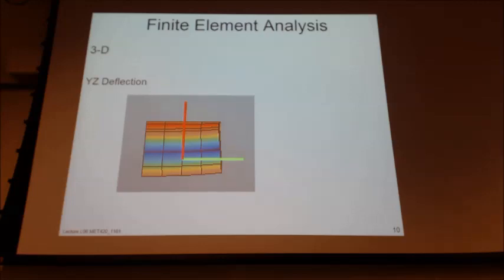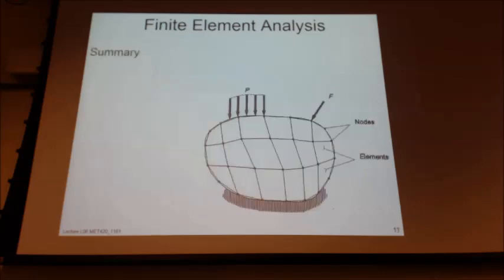And we remember from that graph that I showed last week or so, until you get out to about a 10-to-1 aspect ratio, shear plays a role in your solution. So be aware of that. That was kind of my summary. Anyway, so that's 3D.